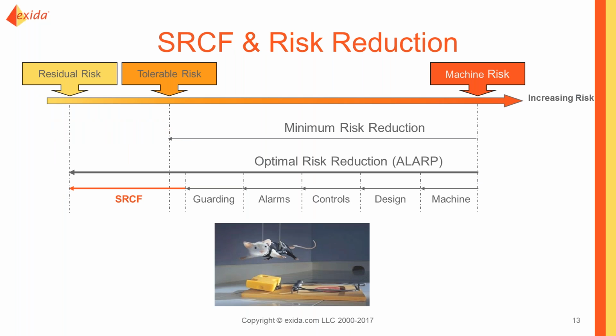When we're looking at safety-related control functions, if we were in the process industry, we'd be talking about safety instrumented functions. The terminology for machine safety is safety-related control function, or safety-related part of the electrical control system, as ISO 13849 discusses it. But we're going to use the terminology out of IEC 62061, understanding that there are similar phrases that might be used in ISO 13849.